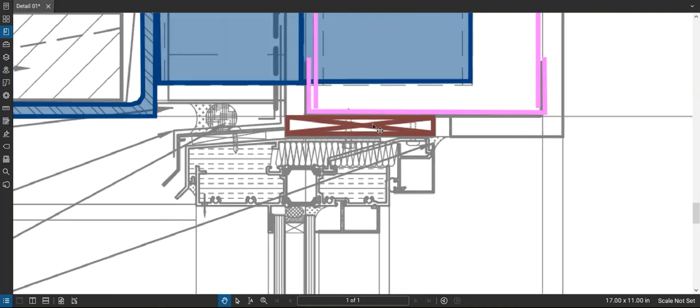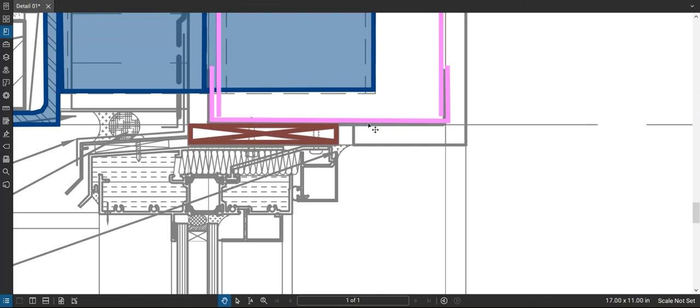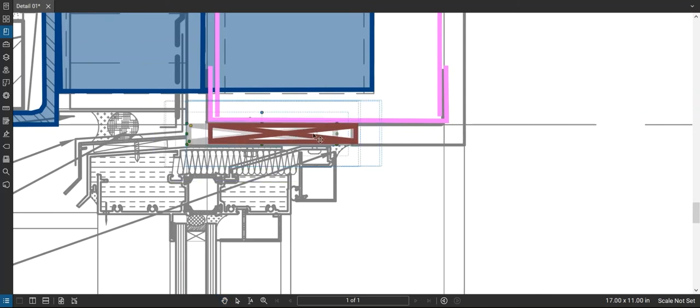So, that's more like a shim. The window, or the opening, I should call it. I don't know if it's a door or window, whatever it is. When it's manufactured, it's going to be a wee bit smaller than the rough opening that was measured on site. So there's going to be some shims to get it squared up and nice and plumb. So that's what that would be there. I actually usually line all my rough openings with a plywood nailer, basically a 3/4 inch plywood nailer, I'd put across there, but anyways, we'll just leave that the way it is.